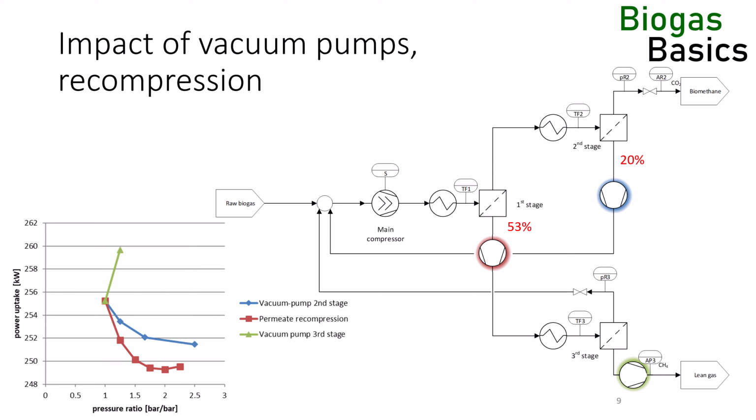I have seen several plants with a blower at the third stage permeate outlet. Often this is to overcome CO2 accumulation around the off-gas stack. CO2 is heavier than air and will sink to the ground in a wind-still environment, or if the stack is near a high building or noise abatement wall. The blower is a futile attempt to push the off-gas out.